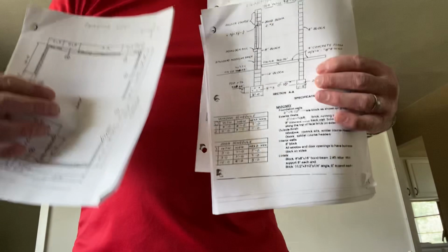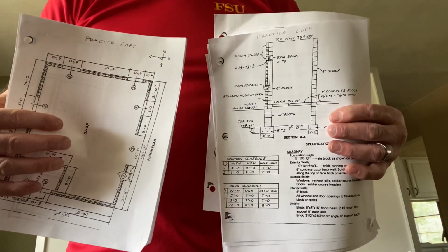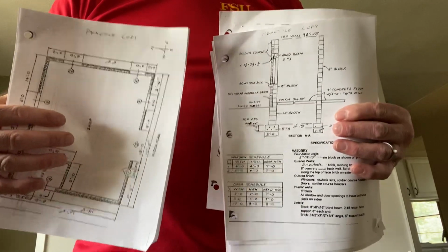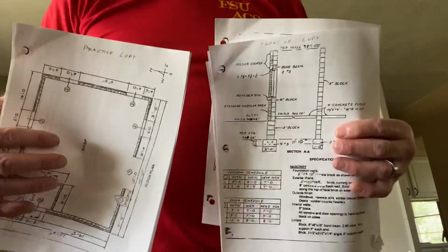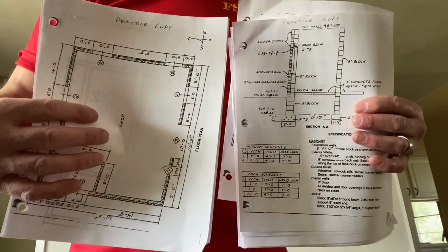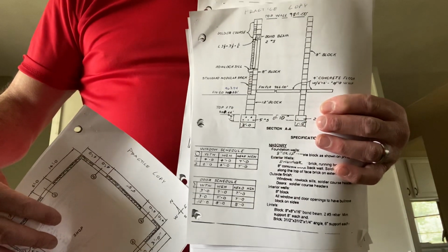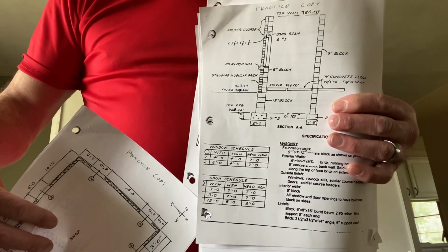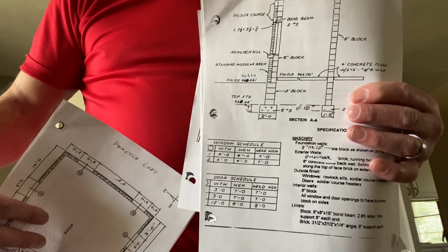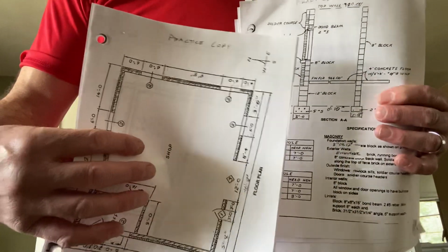So again, I have to use more than one sheet of my print to understand the information I need, because I need to know the height of each window and how many there are, and the height of each door and how many there are. So with the combination of my floor plan view and my window and door schedules, I can determine that information. I can determine the height of each one with my schedule, and how many I have with my floor plan. So everybody refer to your floor plan, or your print, as we walk through this.